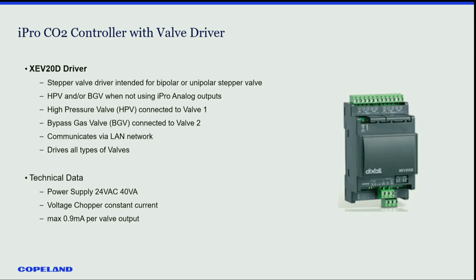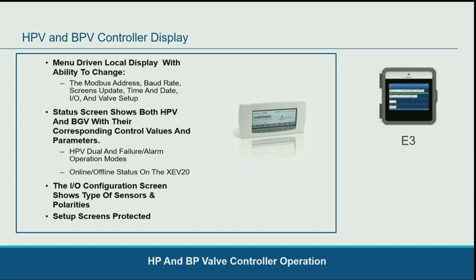This is a driver I mentioned, 24-volt supply, and the driver, the valve driver, as well as the iPro, they have their separate power supply as well. No, you don't want to be sharing it. It's an ungrounded Class 2 transformer.